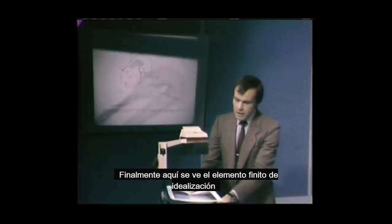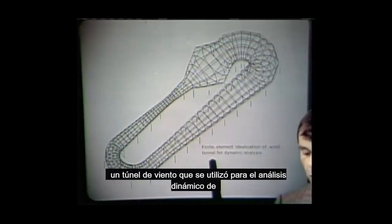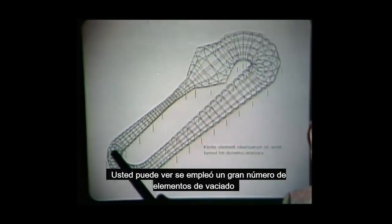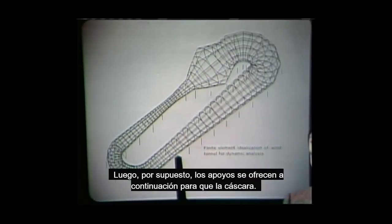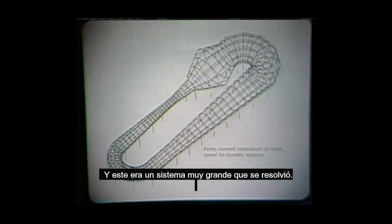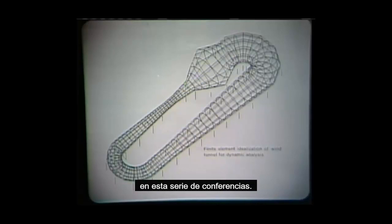Finally, here you see the finite element idealization of a wind tunnel that was used for the dynamic analysis of this tunnel. You can see a large number of shell elements were employed in the idealization of the shell of the tunnel. Then, of course, supports were provided here for that shell, and this was a very large system that was solved, and the eigenvalues of this system were calculated using the subspace iteration method that we will also be talking about in this set of lectures.